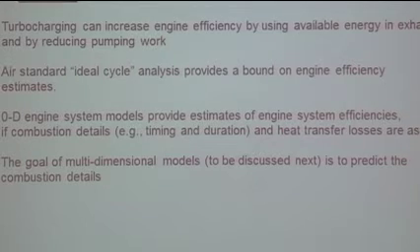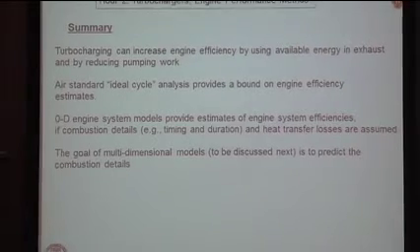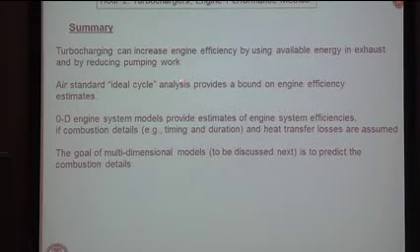Okay, so to summarize, turbocharging can increase engine efficiency by using the available energy that's in the exhaust and also by reducing pumping work. The ideal cycle analysis provides an estimate, if you like, of engine efficiency, but there's a lot of things that it doesn't account for.